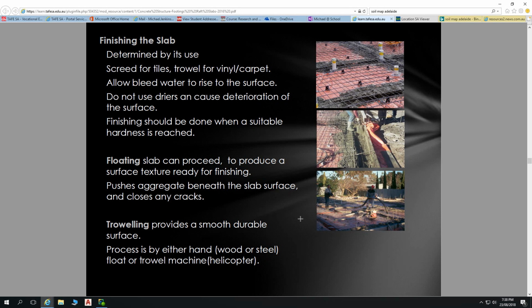After that, when they're doing the slab, you'll have one person. Hopefully they've got a motorised screed, which they can stand up. It's got a motor on it that makes it vibrate, and they can pull the concrete around with this. Otherwise, they'll do it by hand, leaning over with a big aluminium bar and chopping, etc., to move the concrete around. That gets a rough sort of level with lots of lines and so on in it.